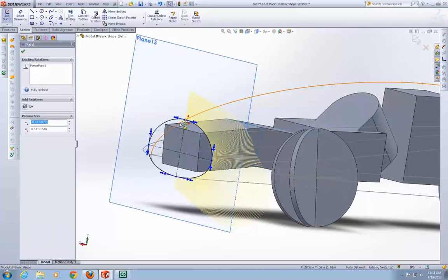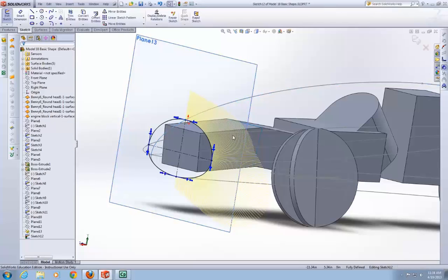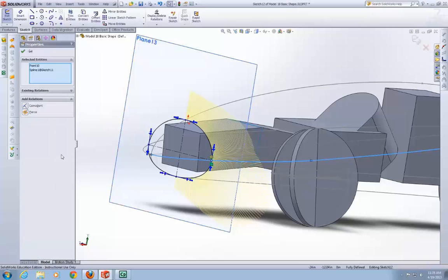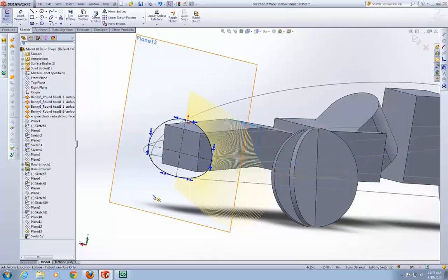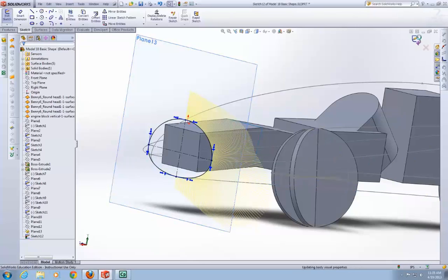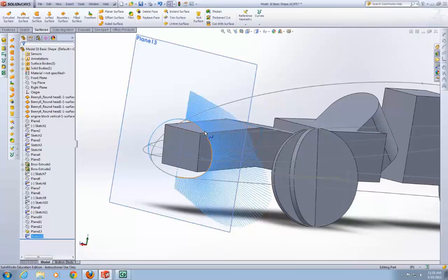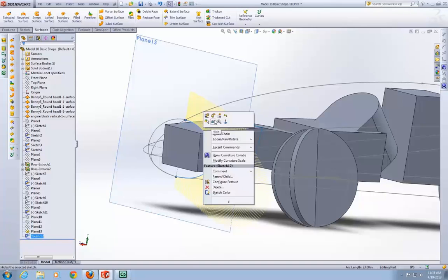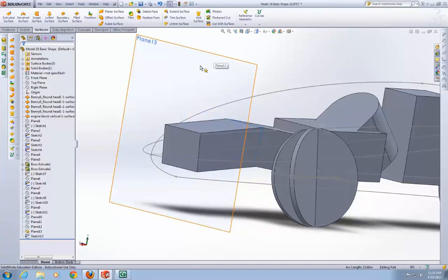Now you have to go back and make sure all the points pierce their respective guide curves. So like right there, make sure it's pierced. Piercing is the key to success. If you don't pierce it, you will fail. So there you go. Turn off that curvature. And that's pretty much the end of this tutorial.